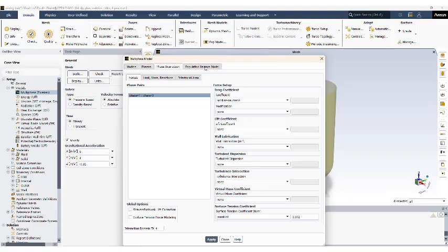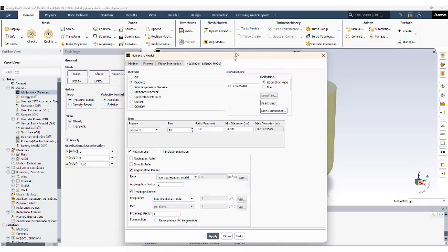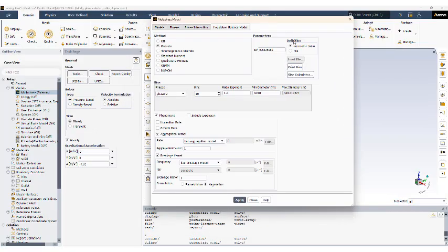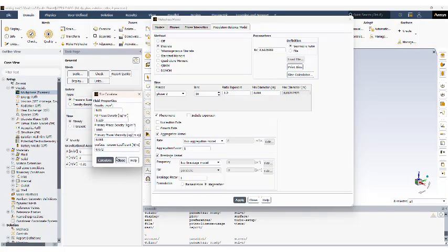Finally, the population balance model. This is a tab that's available. It's set to off by default, and to activate it, you just select one of the methods. Here I selected the discrete method, which I mentioned before. You're tracking bins of particles, and each bin has a specific size. And to know what size is physically reasonable, you can select the size calculator here, which will provide you some ranges for minimum and maximum values for bubble size in this case. So it accounts for the properties of the primary and the secondary phase.